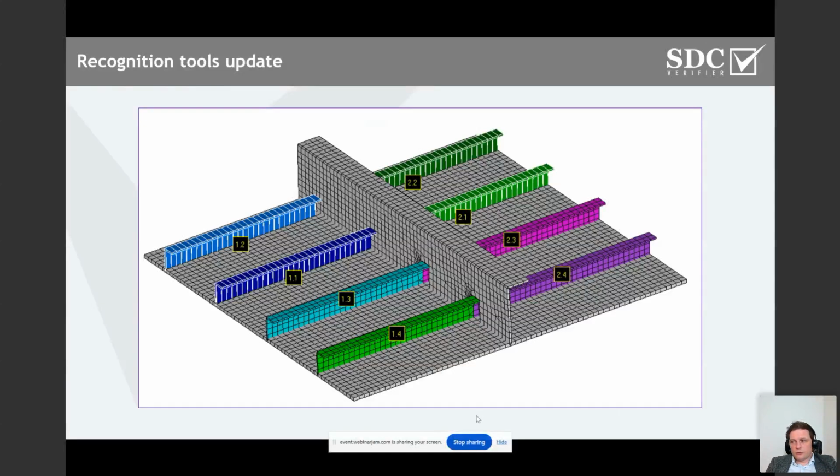But many users have legacy models done like this, or models coming from some CAD software where they have stiffeners modeled as plate elements. And for now, the software is capable of detecting those stiffeners. The goal for now is to include the force summation of the line of the stiffeners into the buckling checks and into the stiffener checks.